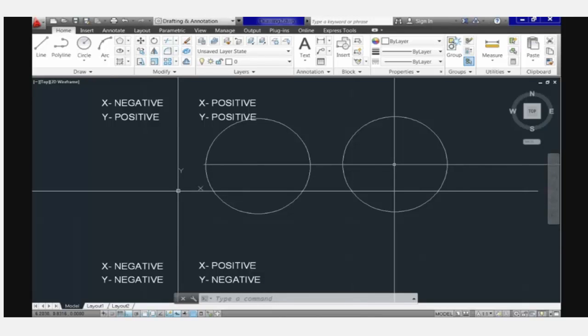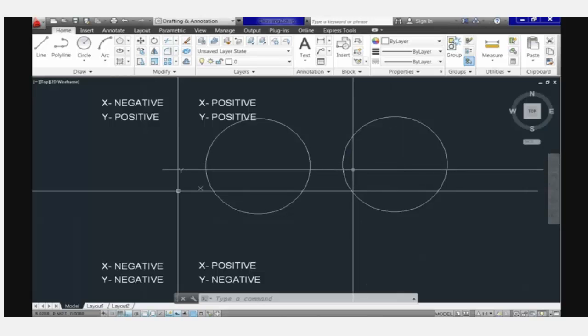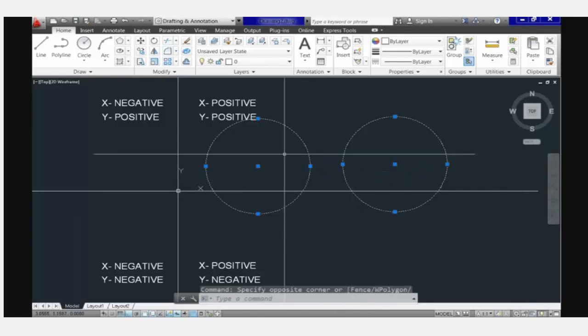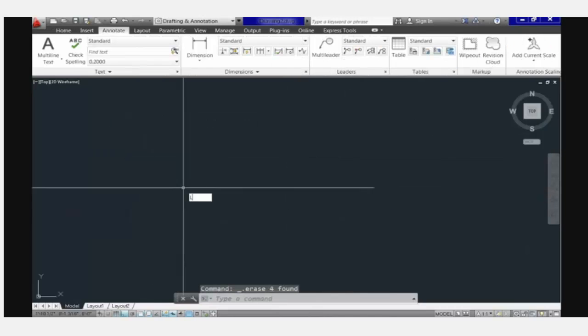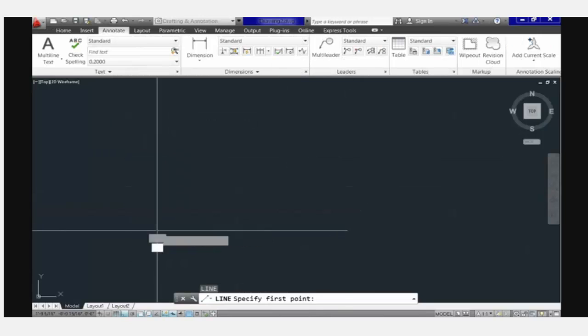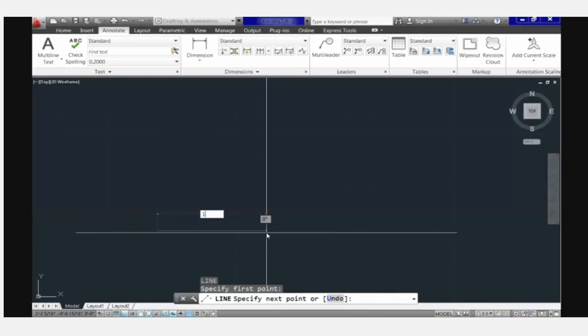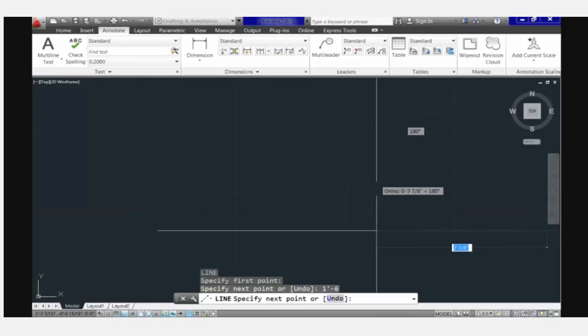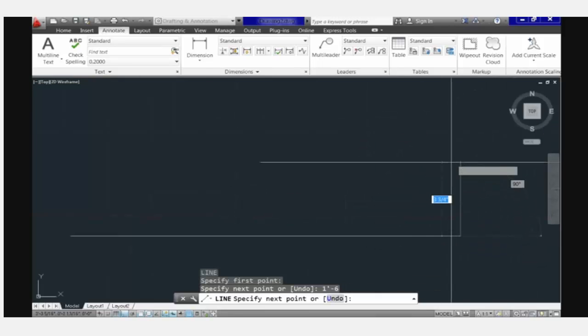An important detail on this is that you cannot use the space bar but a hyphen. If you use a space bar, it will end the command and will accept the first number you input. And the same applies to the architectural units. When you're using it, you need to use the hyphen to separate the feet symbol from the inches in your measurements. However, although you need to tell AutoCAD that you're using feet by entering the feet symbol, you don't need to do so with the inches symbol.